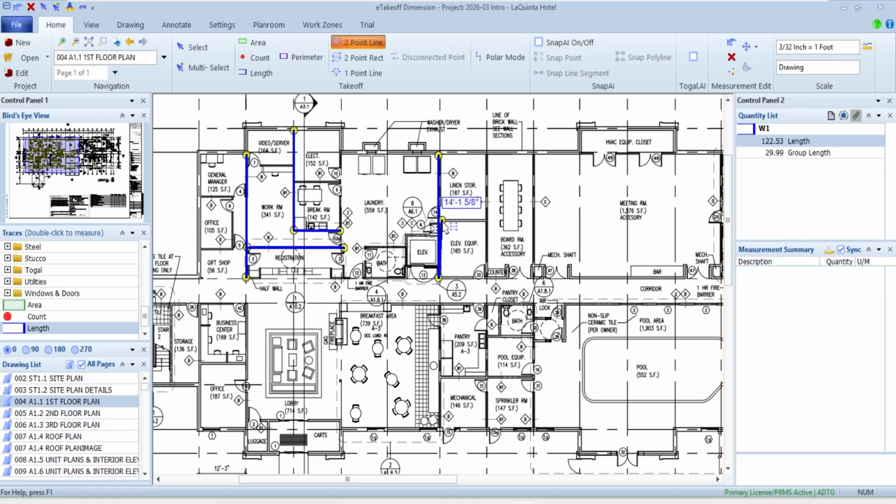So that way, instead of always having to go up and hit the disconnect, this is handy because it lets me associate a beginning and an ending point of a line. If you notice, it drags it over like it's going to continue on, but since it's in the 2-line mode, I can just start, stop, start, stop, start, stop, and it makes it a little bit faster than click, click, G, click, click, G. So that's one note to take a look at. I'm going to just hit escape.